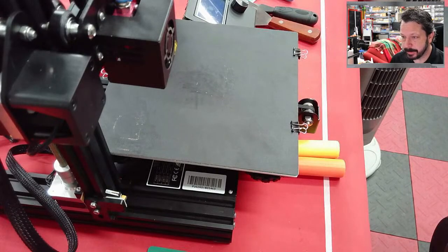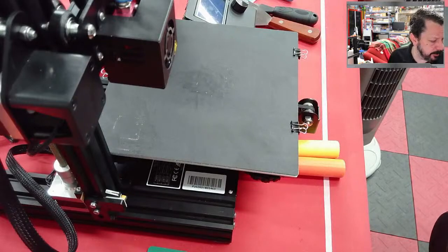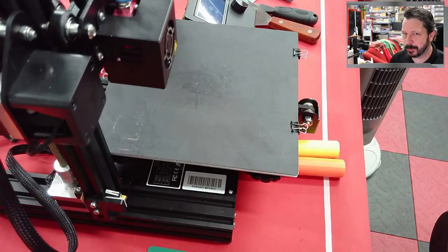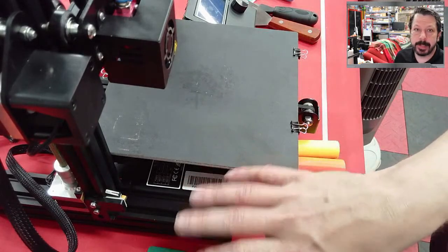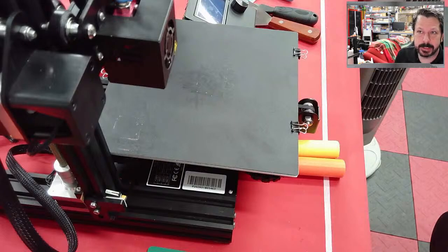The other thing that does cost money is change the bed surface. We'll do that eventually. I have a different bed surface. I don't remember which one I actually got, but typically the ones that I get are a PEI surface. The way this material works is when you heat it up, it bonds with the PLA or the ABS or most materials that you print on it. It bonds with them and holds on to it until it cools back down, and then the parts almost slide off of there. So there are different print surfaces.